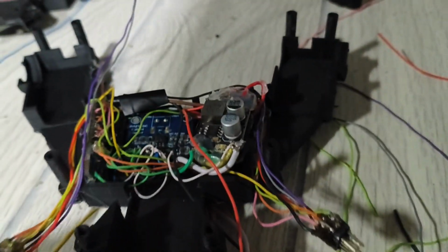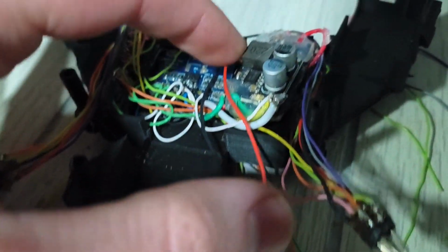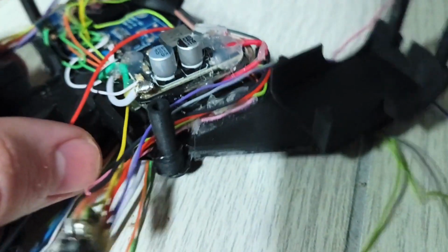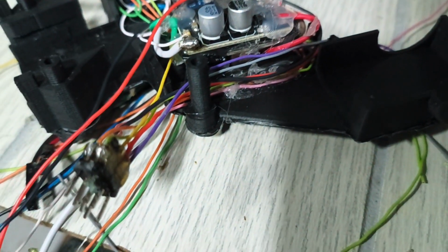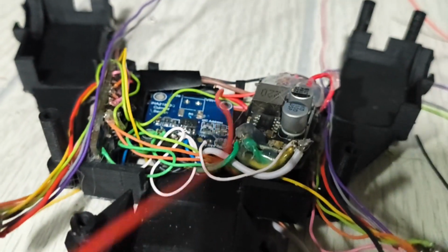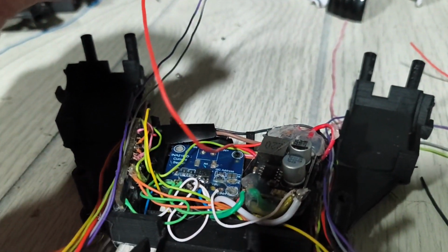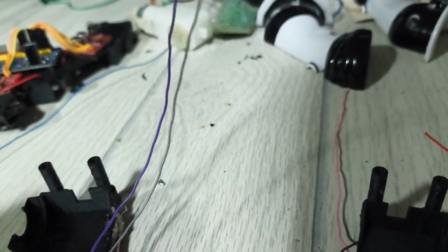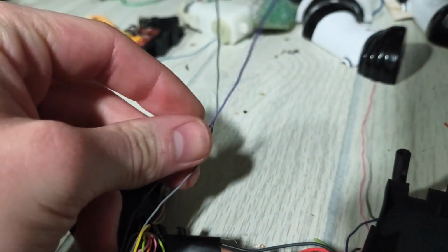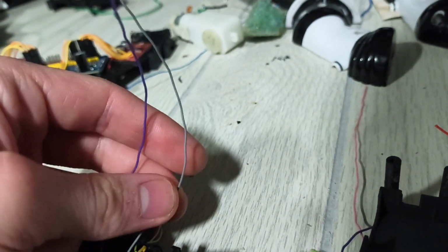You should have the 7-volt input right here going to these two 5-volt boards. And you should have these two 5-volt boards outputting separate 5-volt rails. One goes to the computer and one goes to the rest of the components. You should have just one 5-volt line going out towards the front, and we'll later connect that to the front plate. You should have the motor A and motor B connections, and in this case it's indicated in motor A being bright purple and motor B being this dull purple.